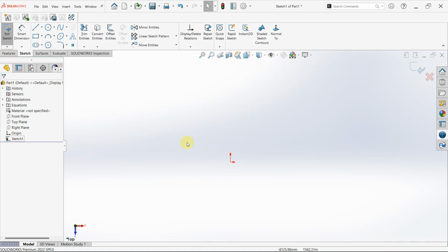So to create a plane in SolidWorks, with time you understand the necessity of planes. The reason why we create several planes is because there are some features you can't use, that you will not be able to use except you create several planes, maybe two or three planes. Then you draw your sketch, you add relationship, and then use the features.